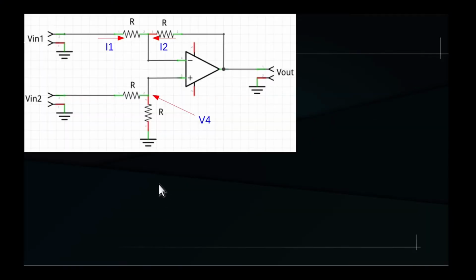An important circuit built around the op-amp is the differential input amplifier. Here is its schematic. First, we can see that the feedback resistor R is connected between the output and the inverting input, as usual. Then there are two input resistors and a fourth resistor that is connected between the non-inverting input and ground. All the four resistors have the same value.